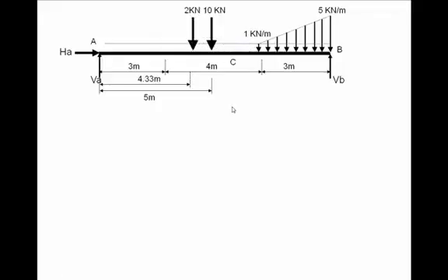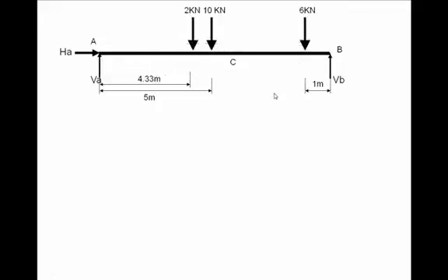So accordingly, we have put here the loads 2 and 6, and the distances are at the centroids of those respective triangles. So in other words, we have reduced that complicated loading system into 3 vertical loads, and now we are going to simply apply sigma Fx = 0, sigma Fy = 0, sigma M = 0 to these loads and the reactions.